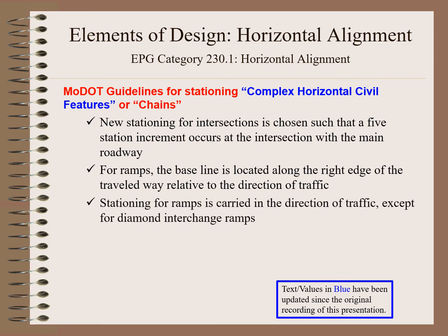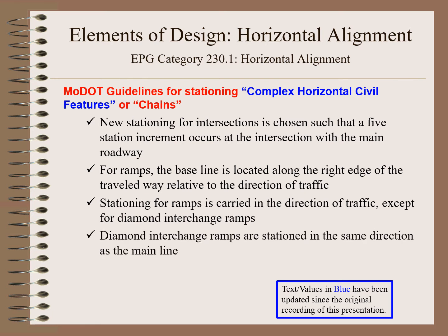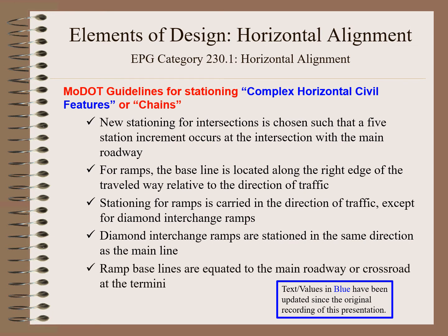Stationing for ramps is carried in the direction of traffic, except for a diamond interchange ramp. Diamond interchange ramps are stationed in the same direction as the main line, regardless of the direction of traffic. Ramp baselines are equated to the main roadway or crossroad at the termini.